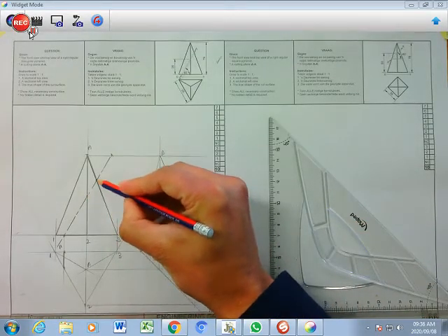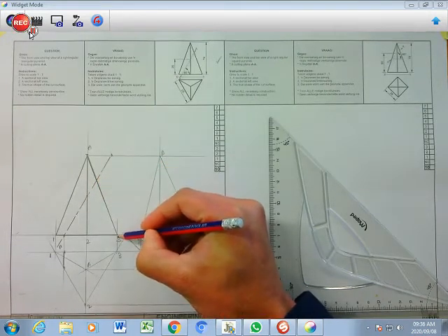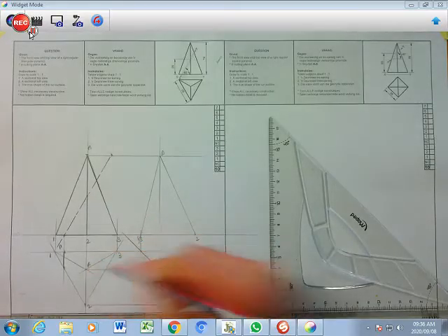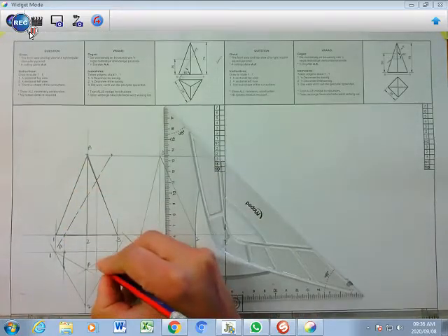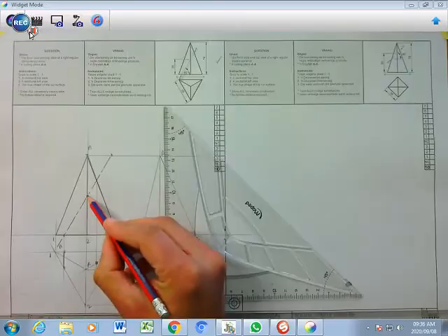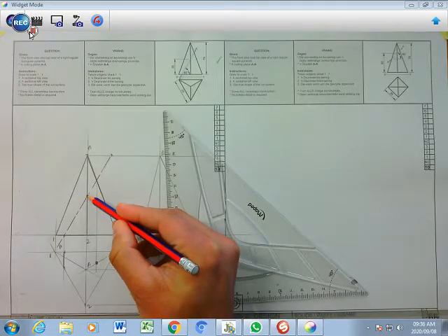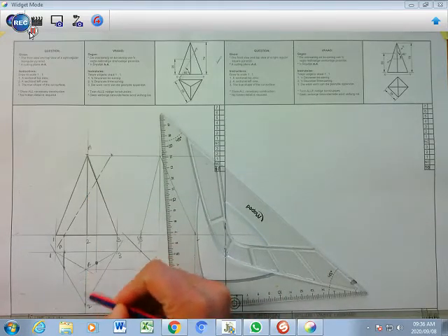I'm going to go there. There's a slant. It cuts on line A3, which is this line here, and I need to bring that down like that on A3. There we go. But then it comes on A2 as well, right? It's going to be on A2 as well. So A2, it's somewhere here, but we're not sure where.